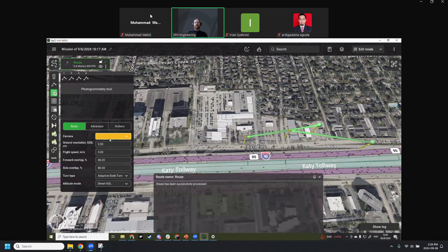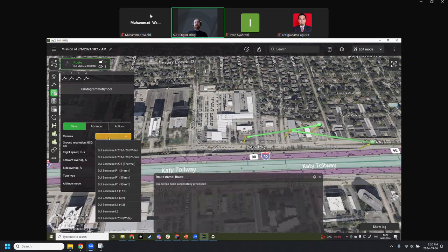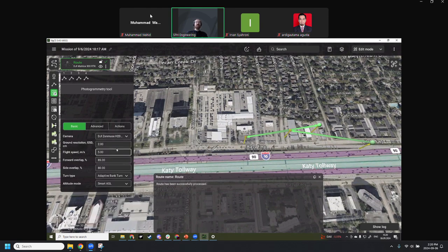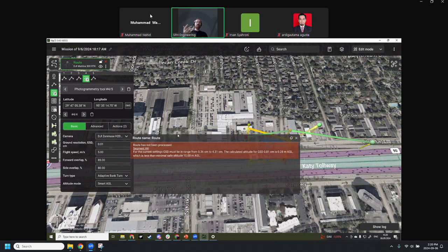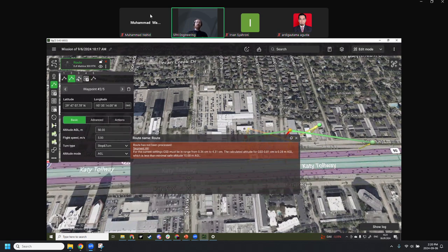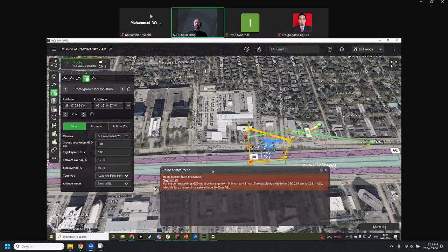Next are the UGCS logs. This window tells you about possible issues or about a summary about your route. So, for example, I'll make it do something impossible and make a route with a GSD of 1 millimeter. And as you can see, it doesn't allow me to do that and warns me about that in the 1, 2, 3, 4th segment. There's a problem why the route cannot be calculated. And it even gives me suggestions on how to change that.